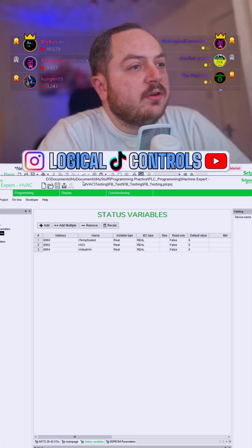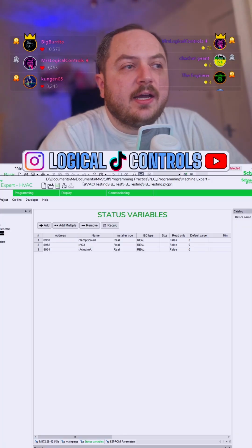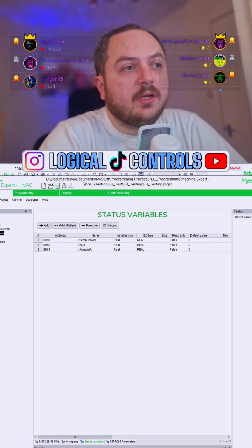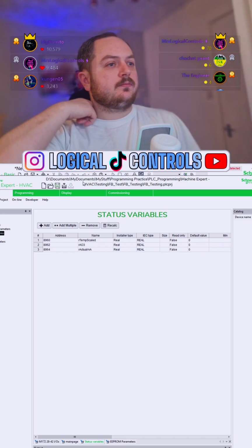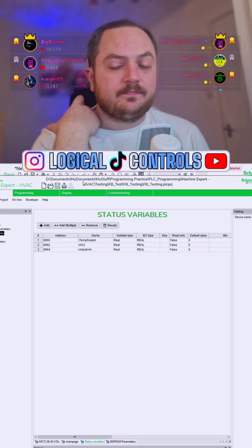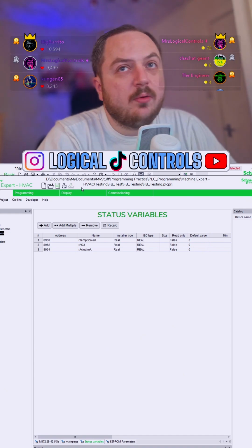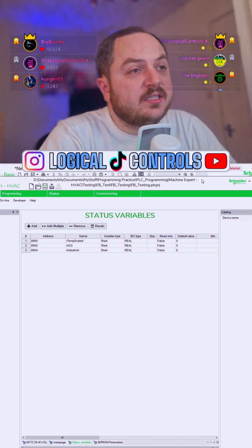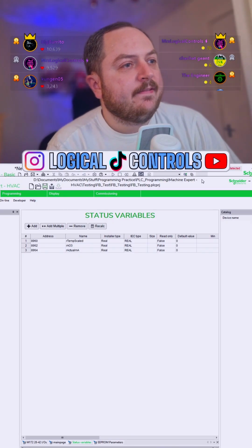Modbus is good for metering and fan control, but must never be exposed on a network. Yeah, I agree, David. I don't put it on like a site network. We make our own little private network for our devices. But yeah, you're right. For what I do, a lot of the time we use Modbus to read from power meters, energy meters. We also use it for device-to-device communications if they're different brands, that sort of thing.